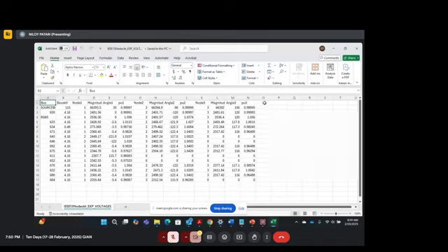And if you can extract how far it is from the substation in terms of distance, then suppose it's a 2000 bus system, you will have 2000 or 2001 rows in the CSV file. It will also have a distance, suppose here in column O, and then you can just plot it. You can put it in Tableau or just use Python or whatever and see how the voltage looks over distance, right?